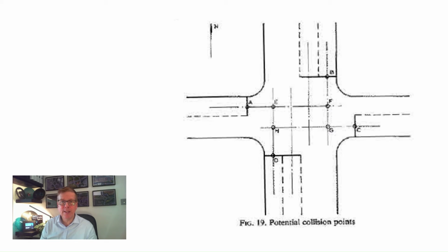The original 1966 Webster and Cobb intergreen example diagram still forms the basis of current advice on determining the relevant intergreen durations. So to establish the intergreen from the eastbound traffic to southbound traffic, phases A to B, measure the distance from A to F, then subtract the distance B to F to find the X distance. Then use the intergreen table to determine the base timing.